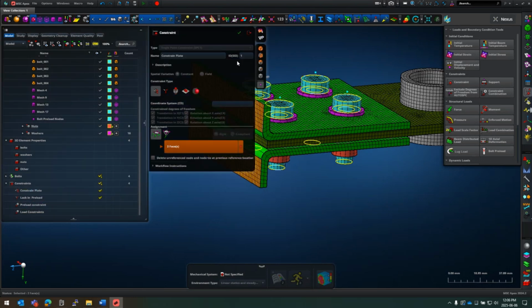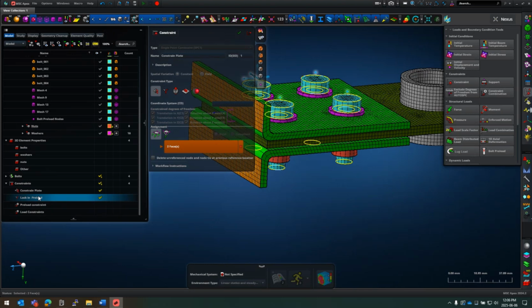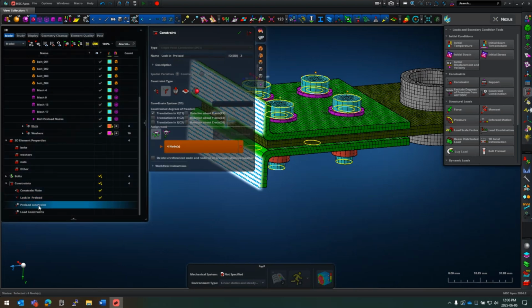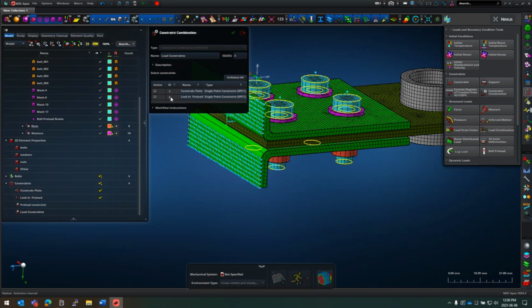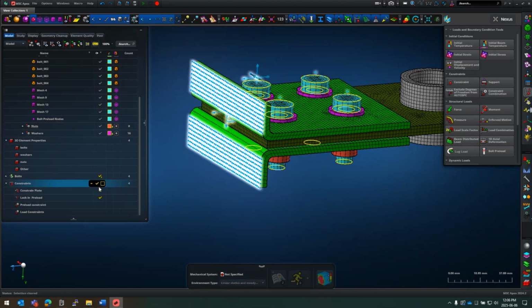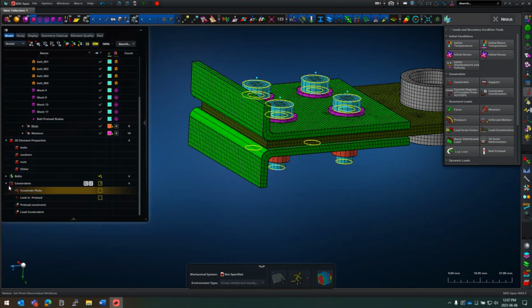And when I just double click, I can see Apex automatically assigned IDs, and this will go straight through to Nastran. If I look at the additional ones, now it's got an ID of 3 and 4, and it's a good idea to be careful with ID so that they don't overlap. By default, Apex shouldn't create overlap, but it's still worthwhile checking it because Nastran allows it and Apex also allows it. Okay, so let's switch these off then.